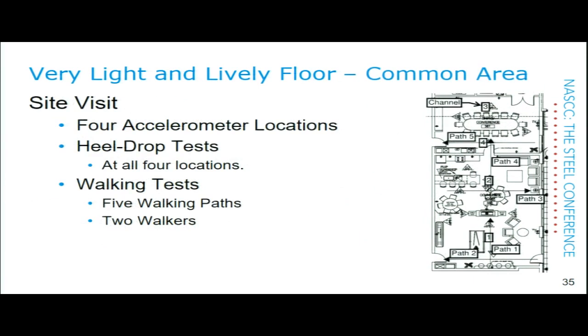Okay, so site visit. Went there, see what's going on, and measure the vibration. This is in the common area. We'll talk about it first, and then the gym area. You see, we have 4 accelerometer locations shown on the right, and we did heel drop tests at all 4 locations, and we did walking tests at 5 different walking paths shown there, with 2 walkers walking several times each to get a pretty large amount of data.